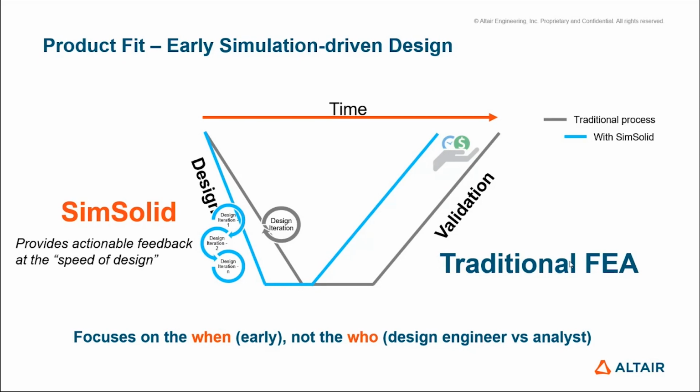Just a note, SimSolid does not have internal CAD editing tools, so you cannot work on the CAD inside SimSolid. But that's not an issue because it allows you to remove and import parts from your CAD software. Because again, as we know with FEM tools, CAD software always has more power than a CAE tool in terms of CAD modeling.